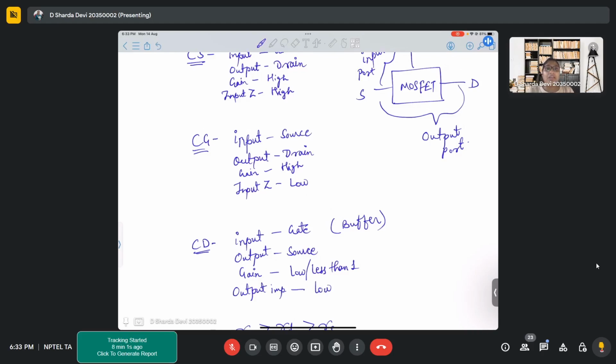So when you see your output impedance, it is actually low. And when we are using a voltage amplifier, like voltage to voltage amplifier, your output is a voltage, so the output impedance of the amplifier should always be low so that all of your voltage transfers to your load. That is the idea. So depending on which type of amplifier you want, whether it is current to current, voltage to current, voltage to voltage, or current to voltage, the characteristics of input and output, mostly impedances, change depending on loading effect.